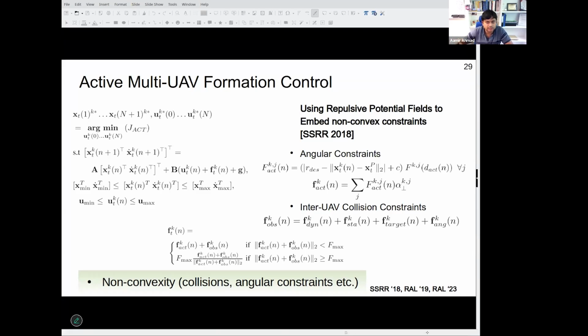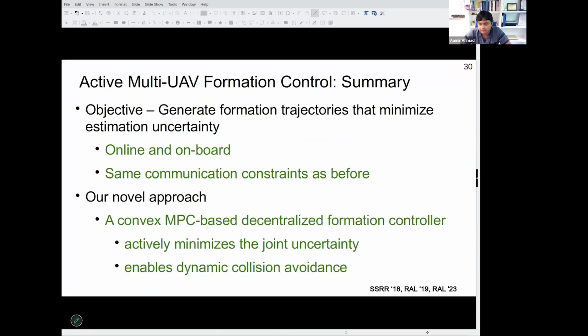What it solves is that the MPC can immediately produce results to move to the next iteration, but local minima might appear. In that paper, we also showed several heuristics, observing the gradient of the objective function and so on, to detect these local minima, and then we can come out of them by applying some external force in the same linear dynamics constraint.